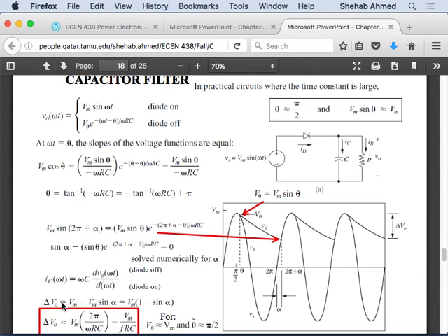They will be clear in the homework. They tell you you're discharging at twice the rate of your input sine, or something like that. Right? They will be very clear. It will be clear where something is a case where the ripple is small versus something where the ripple is large. Something where the ripple is large, you cannot use this. You have to use the regular equations. Calculate theta, calculate alpha, do the subtraction. We clear on this? Yeah.